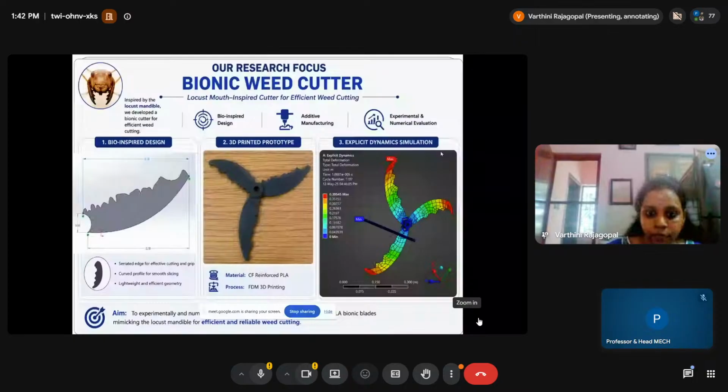Most research is only on thermoplastics, like PLA, ABS, PETG, nylon, PEI. So apart from these thermoplastics, we can also have different classes of materials being printed in FDM. You have to choose the printer according to the material type. If you are using FDM, most of us will be working on PLA only, because PLA is easily printable. It doesn't require much temperature. So even a desktop printer which goes up to 300 degrees Celsius can be used.